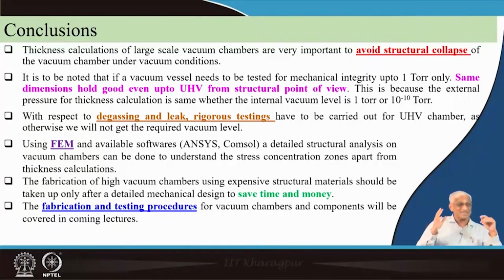So chamber design is not only mechanical design. Outgassing design, welding efficiencies, and window materials, flanges, couplings, many things are connected to the chamber. So it has to be dealt with as a whole, as a system, but the chamber is of course the main thing. That's why we are today discussing the chamber design.